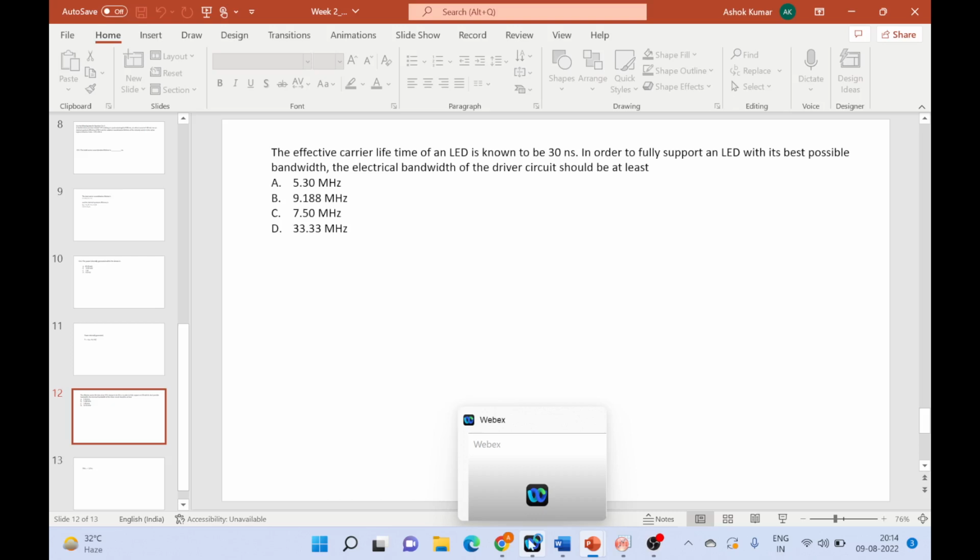You plot the output power of the laser against the input power, make a linear fitting of that data, and find the slope. Whatever that slope becomes gives you the efficiency. Jonek, am I right?